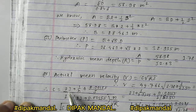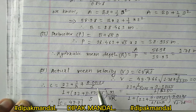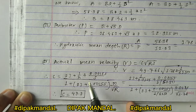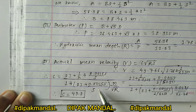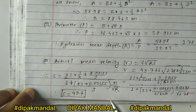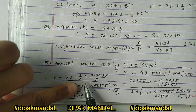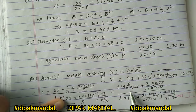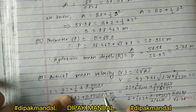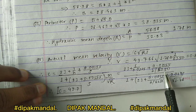Okay, for C we use the formula for calculating the value of C. We use this formula: C equals (23 plus 1 by n plus 0.00155 by S) divided by (1 plus (23 plus 0.00155 by S) times n by root over R). Okay, and all these values are known. In 23 plus 1 by n, the value of n is already given in the question, that is 0.0225. Okay, so we just take this value plus 0.00155 by S, and the value of S we already calculated, 1 by 6250.